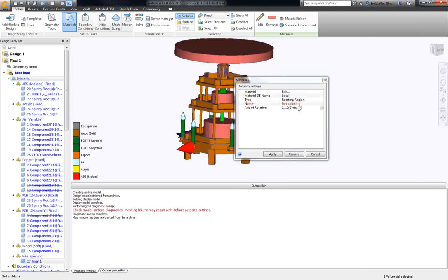Because my design change was moving the blades, but I could possibly just leave the blades in the same orientation, but move them higher, where maybe my air velocity has already picked up a little bit more, being further away from the flame. That would be another possible design change. And what we want to see is the rotational velocity of our whole carousel. So once I see that that's been relatively hanging at the same point and my VY isn't changing, then I know that I'm sitting at a relative steady state.